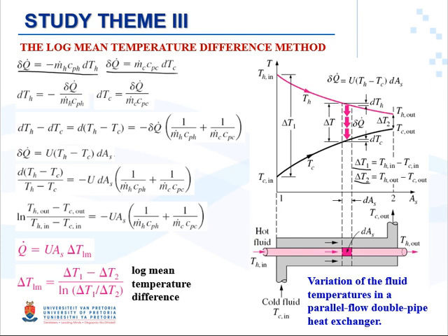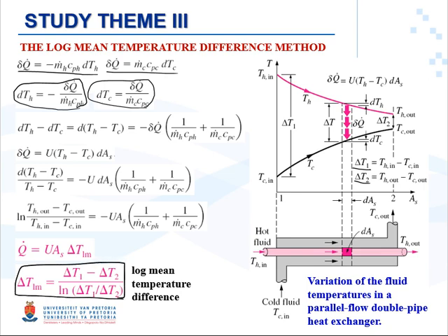So delta T H, delta T C. It's a little bit of mathematical manipulation. And d of the temperature hot minus the temperature cold. Just write it, and if you take all those steps shown here, you can find this correlation that we call the log mean temperature difference.